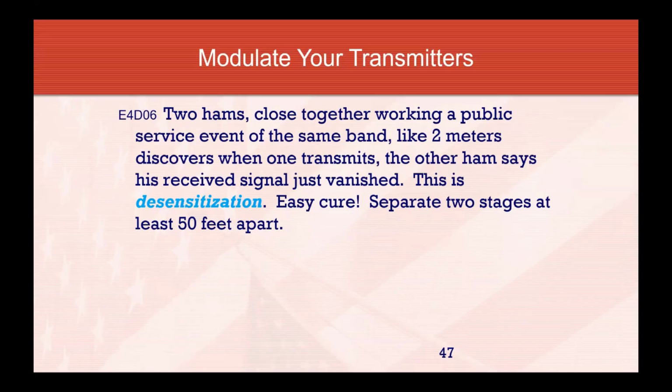It's been swamped. Conversely, when somebody talks on Echolink and Echolink is broadcasting, then my radio goes ballistic and I can't hear what the people are saying there, because my radio gets desensitized because they're just too close together. And then one overloads the other in its receivers. The receivers are not good enough to separate those out at those frequencies.